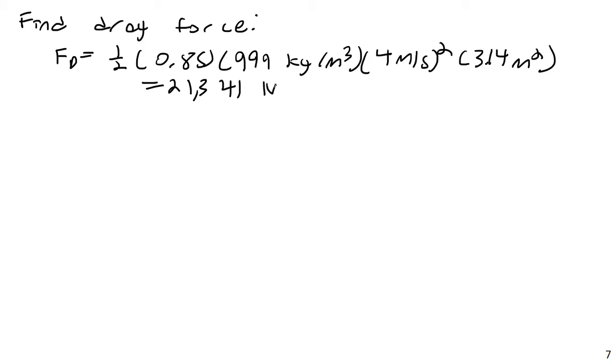21,341 newtons. Then if I wish to find the power required to do this, this would be P equals Fd times V, so the force of drag times the velocity, just a basic physics equation.